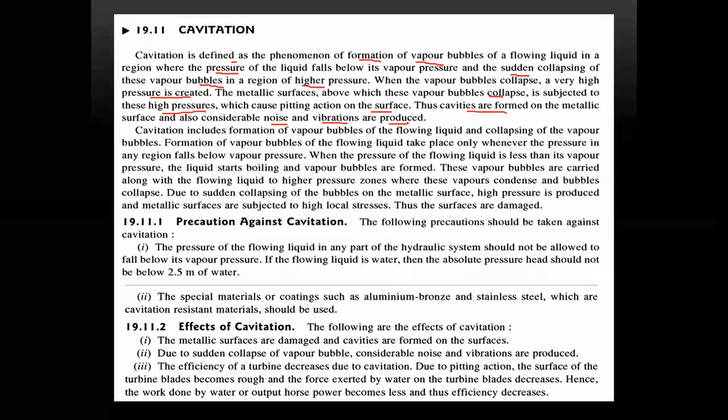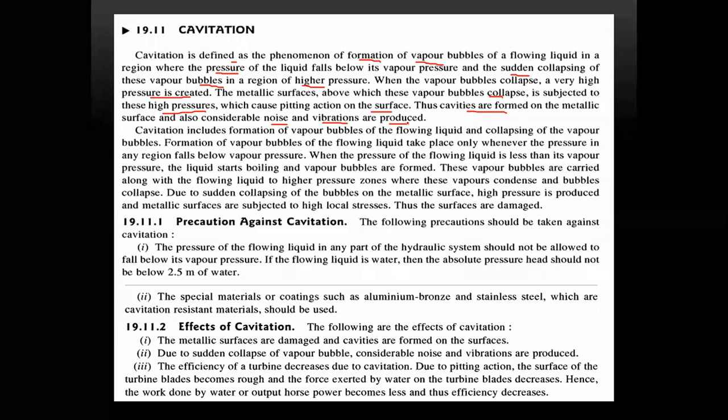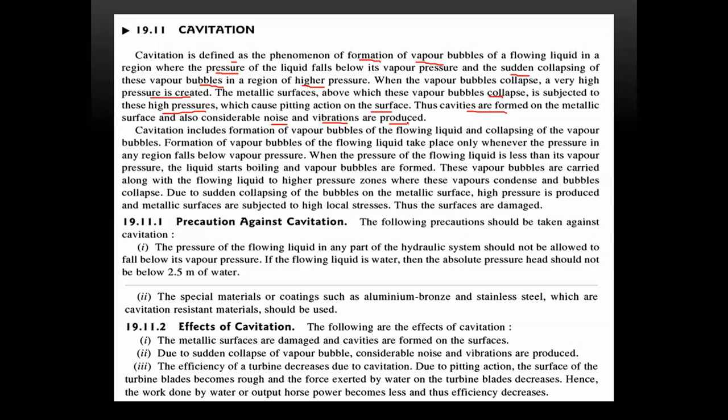So simply you can draw a simple impeller, దానికి ఒక 2-3 veins వేసి ఆ veins edge లో టిప్ దగ్గర చిన్న చిన్న బబుల్స్ లాగా హోల్స్ వేశారనుకోండి, that is nothing but cavitation. ఎలా వస్తుంది cavitation? So whenever the water is pushing from the impeller center to the outside of the exit through the veins, the pressure bubbles అనేవి ఎక్కువ ఆ tip of the vein దగ్గర form అవుతుంది. So because of this pressure difference, these bubbles will blast.